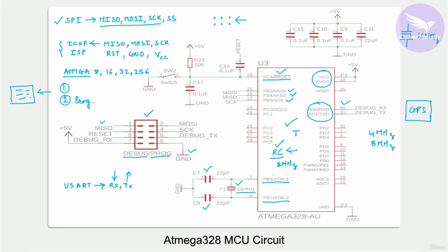And inside this microcontroller, there will be some more circuitry, like some buffers, which are also part of the Pierce oscillator circuitry. But externally, in order to operate this controller with the help of an external crystal, we need to connect an external ceramic crystal, and along with that, we need to connect these capacitors for stability purposes.